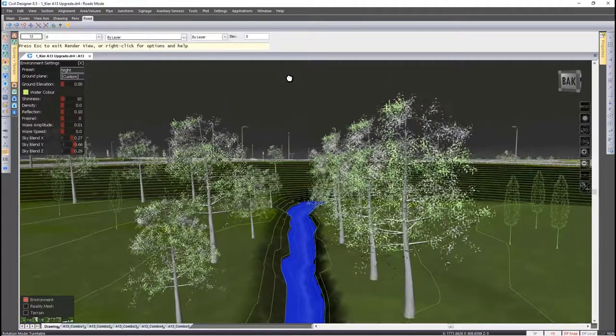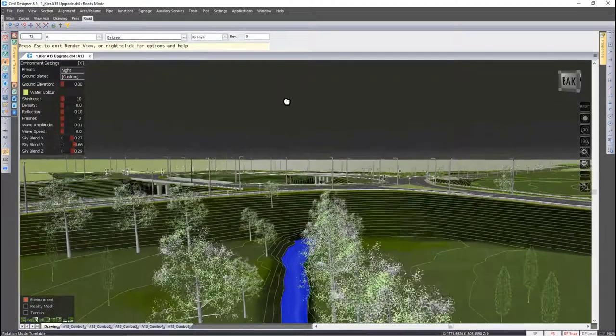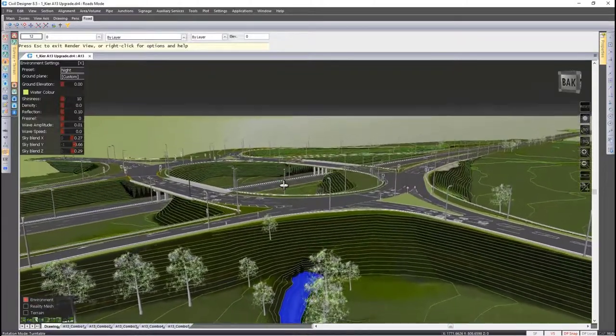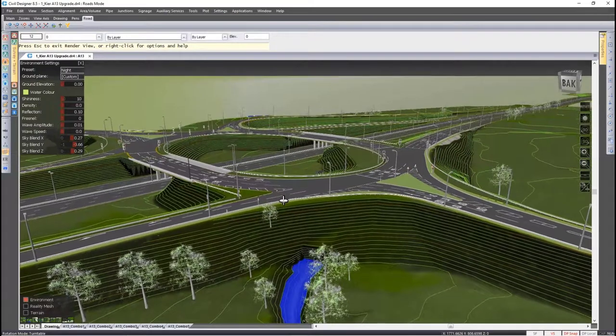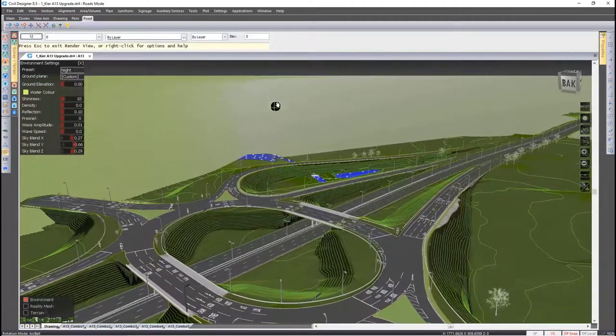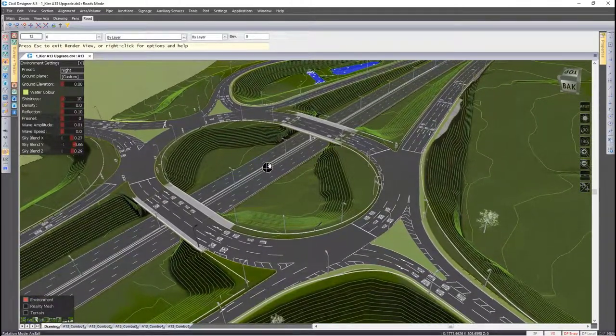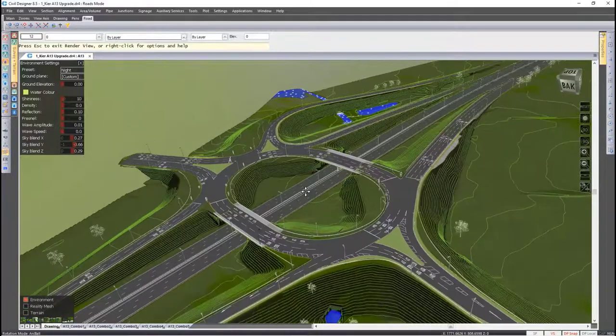Turntable is a very controlled movement. Pressing Ctrl at the same time results in the rotation of the drawing as if it were a turntable that is only rotated around the Z-axis. This avoids any unwanted tilting from occurring. In most cases, you should use the turntable. The other option is an arcball rotation. As the name suggests, it rotates the project as if there was a big transparent ball around the portion of the drawing you are looking at. Therefore, this movement is more evident.